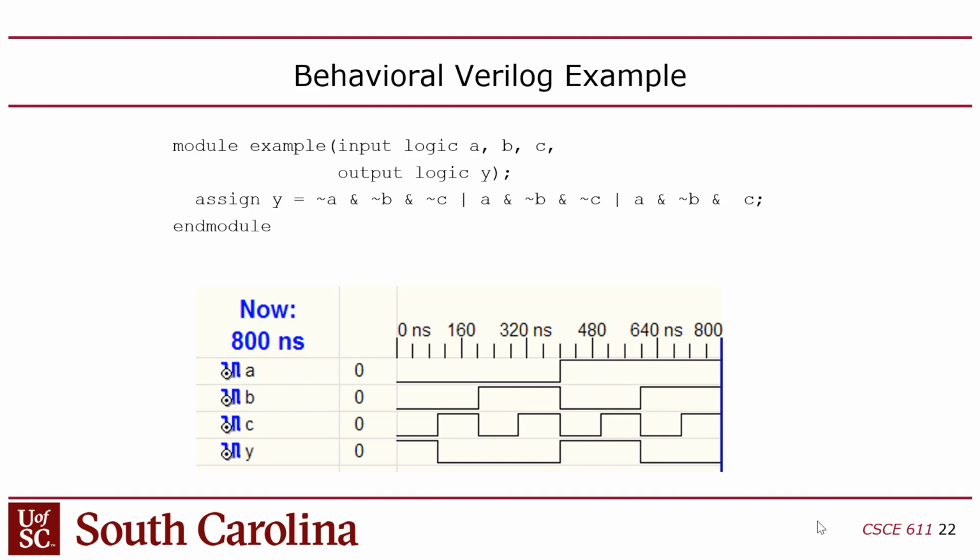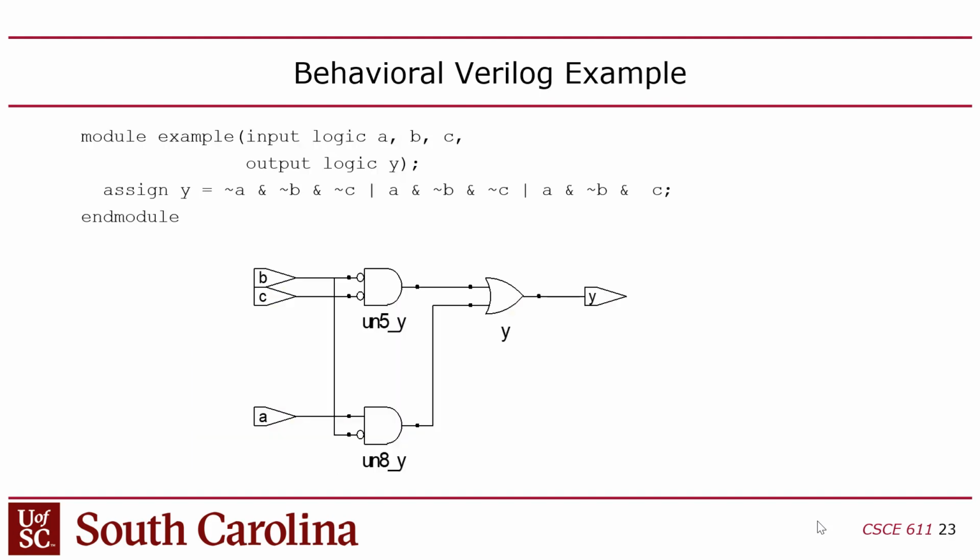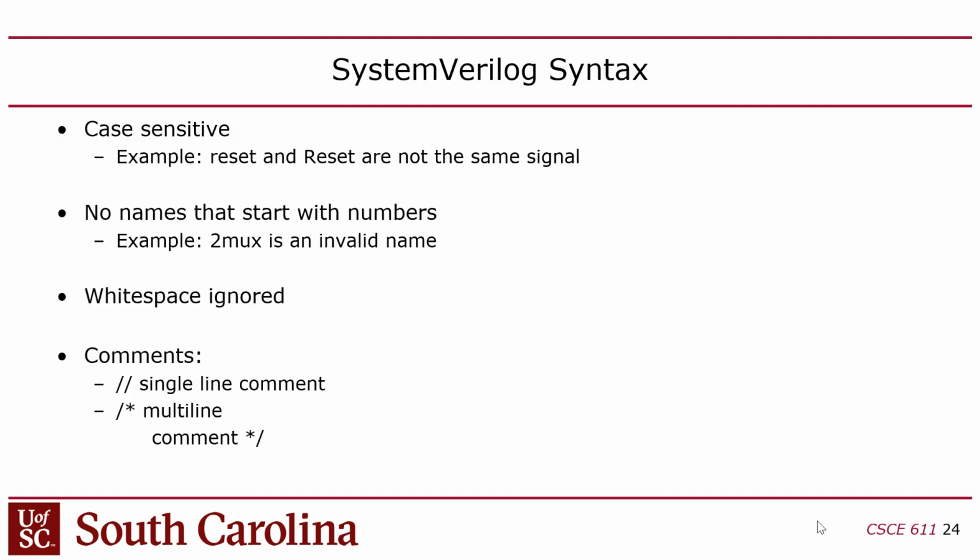Okay, then when you synthesize that, the synthesizer minimizes the circuit, so even though it appears that I ought to have a 3-input OR gate and 3 3-input AND gates, I don't have those for some reason because it minimized it. It simplified the circuit into an equivalent form.